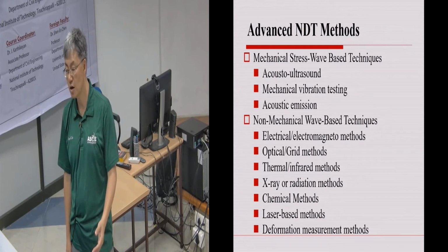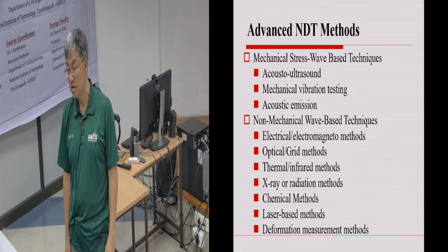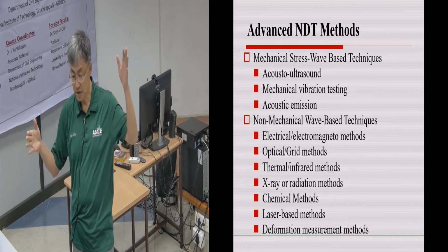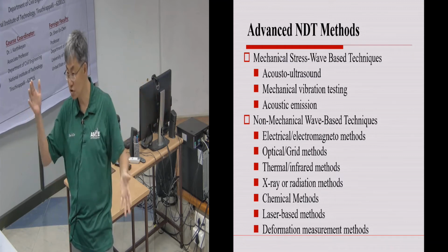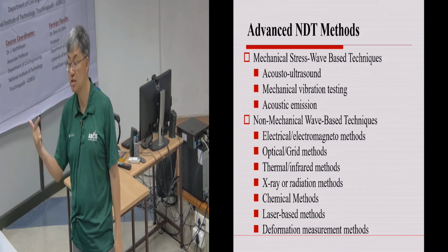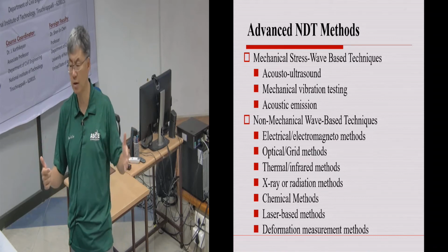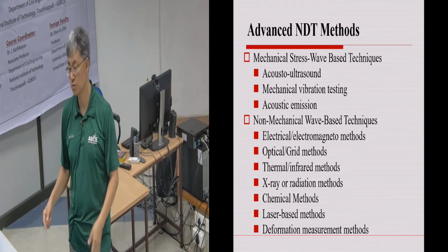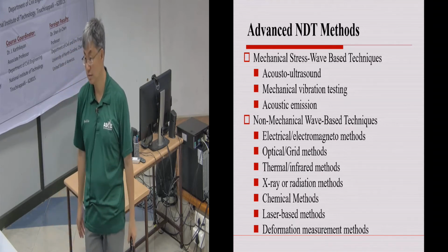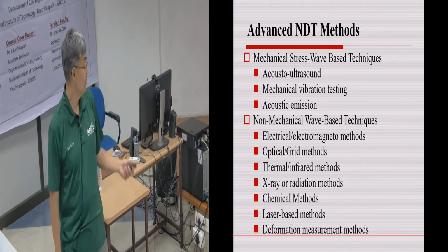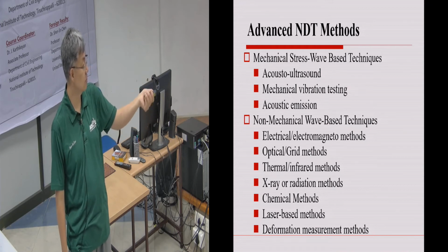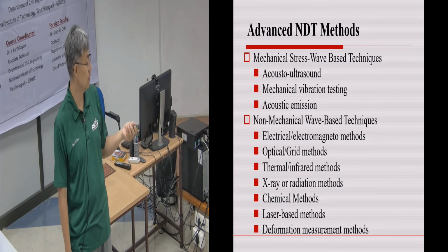For nuclear concrete, my student has done it: even for a 2 feet thick wall with a lot of rebars, even if you have a 1,000 degrees differential of thermal gradient moving, you cannot use an infrared camera to see anything, because it takes a long time for heat to go through concrete. So it's not necessarily the right technique for that kind of application. And then several of those techniques are traditional non-destructive testing methods.